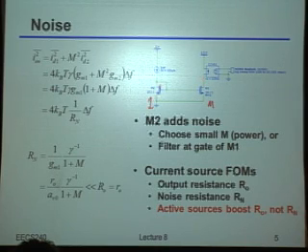But we have a second one due to this mirror device here, right? Where much like we talked about a second ago, this mirror device is connected basically as a diode. But you can think of this as, if I'm doing the current mirror for my signal current, I'm also going to be mirroring the noise current as well, right? And so in the noise calculation, rather than just getting 4kTγ times the gm of the actual output device, now I'm going to also get the gm of this mirror device times that m factor squared, right? Because again, we're working in variances here, not in standard deviations, okay?